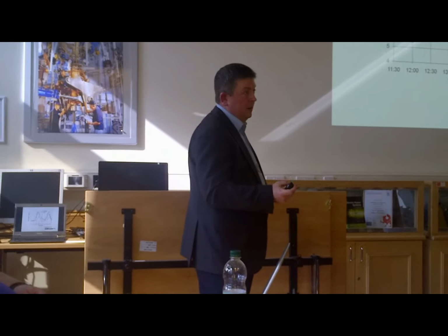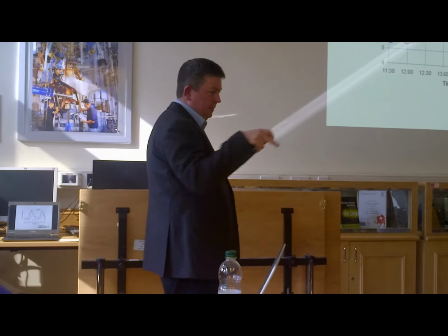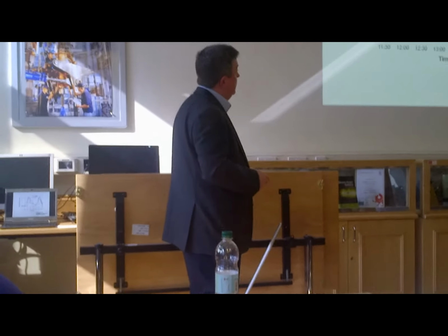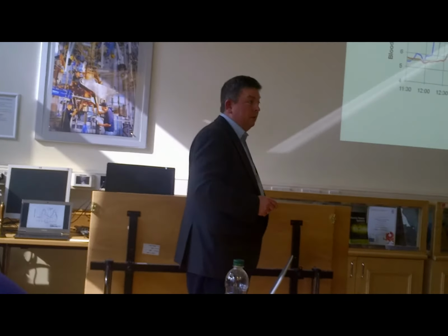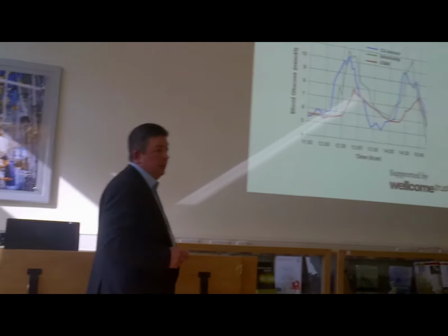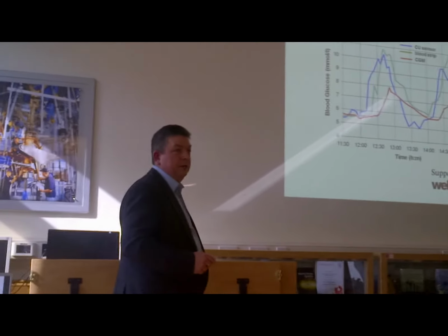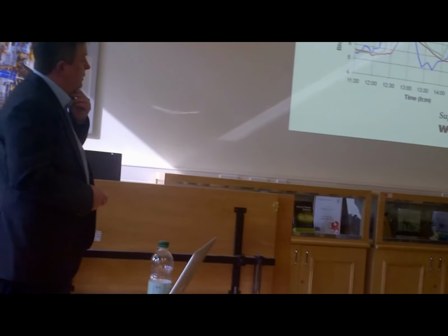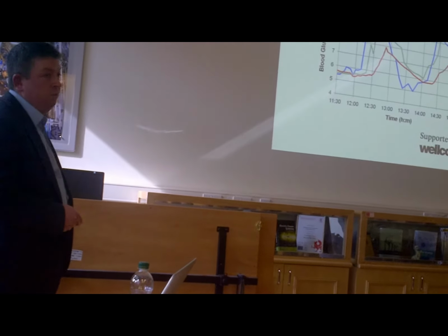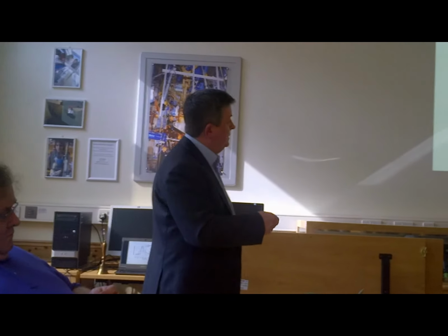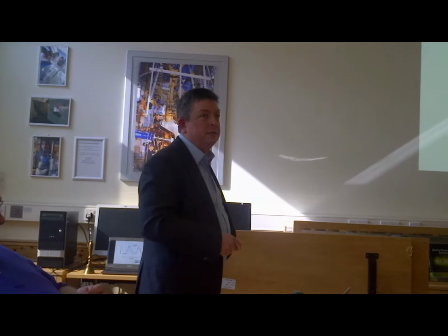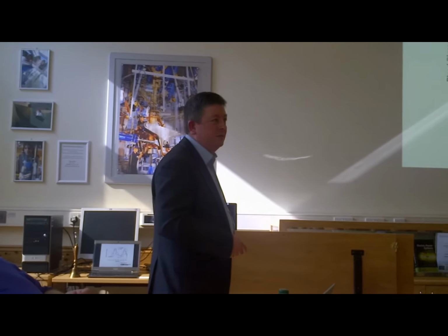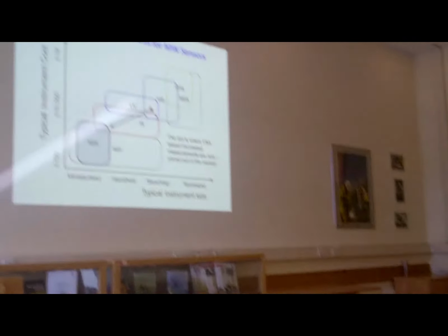And you notice the red one isn't too good because, A, the signal is washed out quite a lot, and the other thing is it's delayed as well, because the continuous glucose meter doesn't sit in blood. You shoot it into your torso and it actually sits in interstitial fluid, and the uptake of glucose in that is different to that in blood. So what we think we're measuring is mostly blood, and we get pretty good correlations between what we measure and what we get for the invasive method that involves either a glucose analyzer or the conventional blood strip meters.